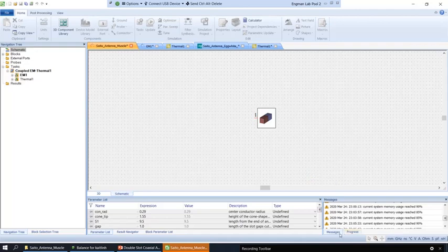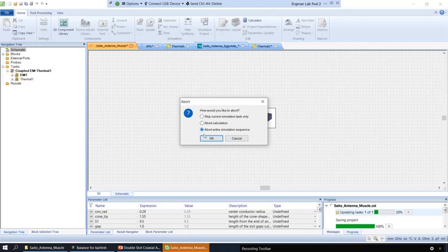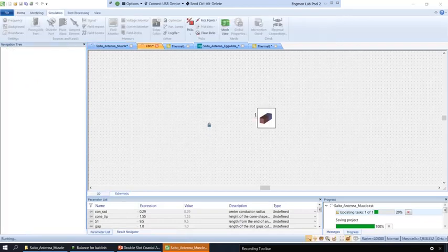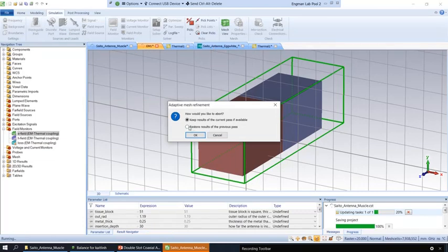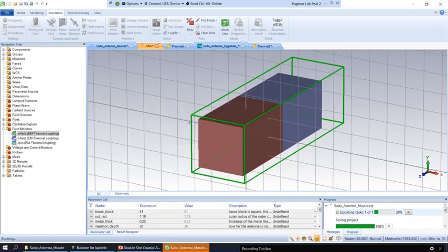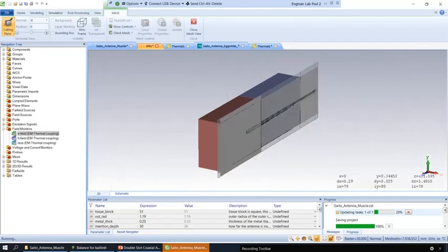So why is this happening? Typically, it is because your mesh is too fine. So let's investigate this a little bit. Remember, if we go to the simulation tab, we can look at mesh. Remember, what's happening on a small level here is this has been subdivided into a bunch of little sections, and it's running calculations on each of those sections. And so you can see that if we go into this mesh view.